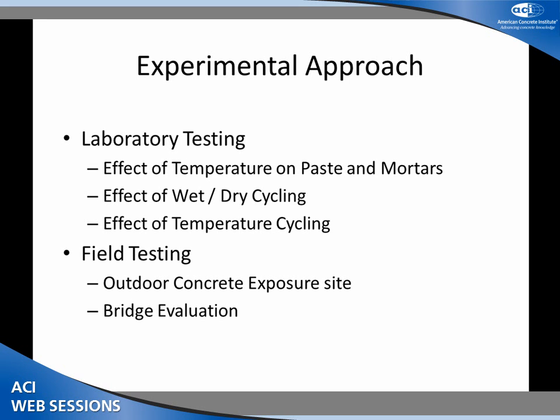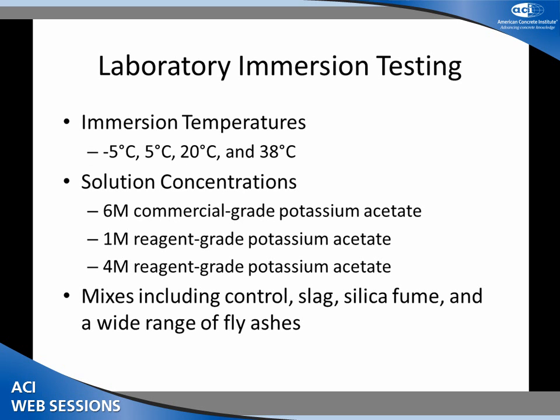So we looked at this, we did laboratory testing. We also did some field testing, and I'll just jump right into the laboratory testing. So we did paste and mortars which we immersed in potassium acetate solution, and we did that at 4 different temperatures: negative 5C, 5C, 20C, and 38C. So pretty much from below freezing all the way up to about 100 Fahrenheit.